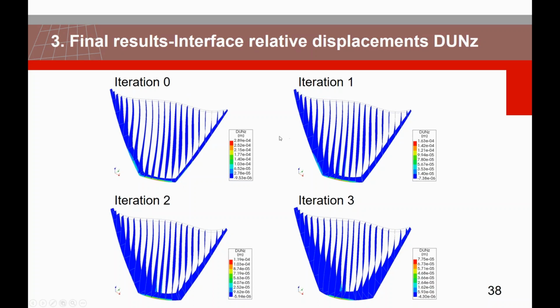But as we're adding concrete, we can see that this area is getting smaller, while all of the openings are happening closer to the toe of the dam. By adding even more concrete, we see that this area has diminished. And in the end, for iteration 3, we can see that these openings are happening only around the crown cantilever section.